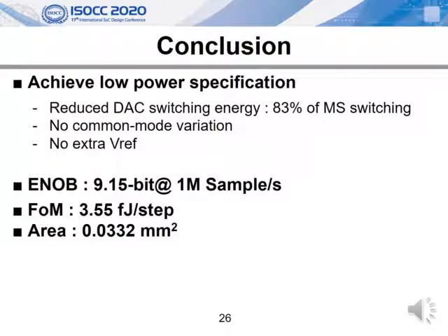The chip is implemented in a 28nm process. The simulation result shows the FOM of 3.6 femtojoule per step at 1 megasample per sec with 1 volt analog supply and 0.4 volt logic supply. The total area is 0.0332 mm square. The proposed technique only requires 1.2% of the total area.